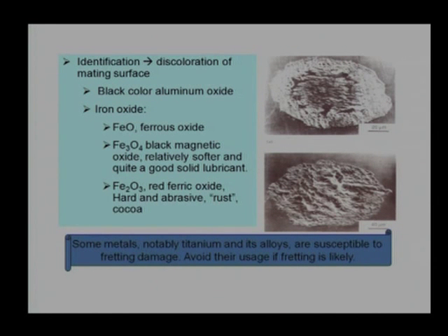When they get oxidized, their hardness also increases, and that is why they increase the wear rate. So many times we use the word fretting wear, and many times fretting corrosion, because the start is a fretting mechanism leading to corrosion and an overall increase in the wear rate. There is mechanical action continuously. So fretting corrosion and mechanical action is fretting corrosion wear.